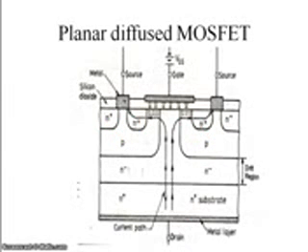Now P regions are diffused in the epitaxially grown N minus layer. Further, N plus regions are diffused in the P region as shown. So as before, a silicon dioxide layer is added, which is then etched so as to fit the metallic source and gate terminal.